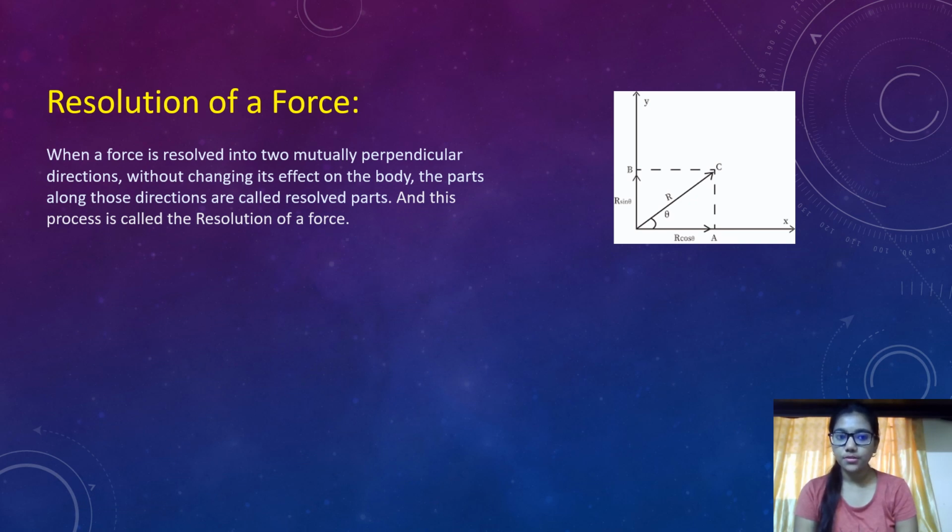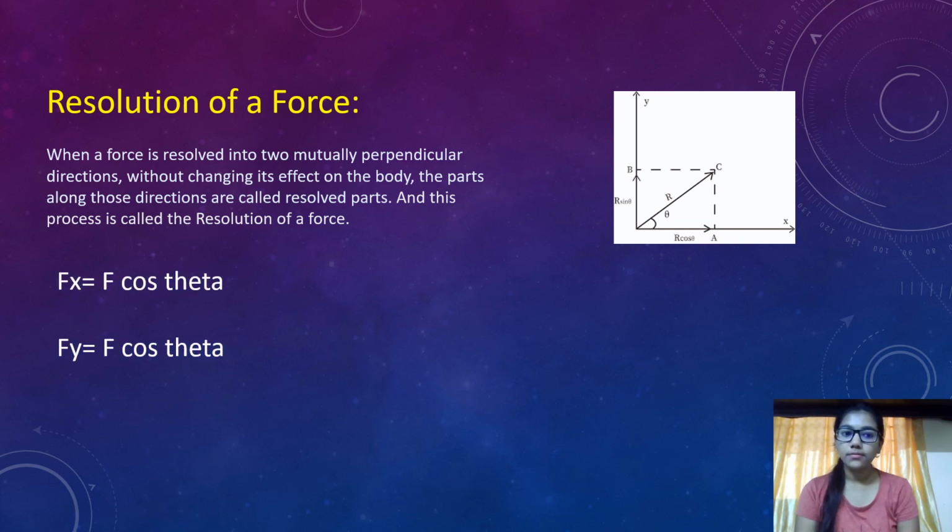Resolution of a force. When a force is resolved into two mutually perpendicular directions without changing its effect on the body, the parts along those directions are called resolved parts, and this process is called resolution of a force. Fx is equal to F cos theta, Fy is equal to F sin theta.